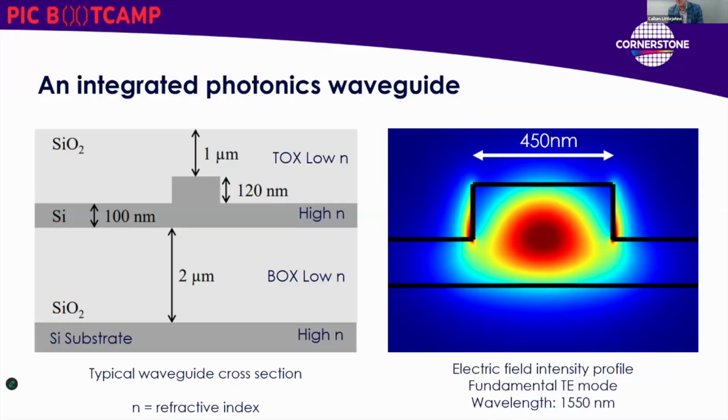This is probably my most technical of all of the slides. I just thought it'd be worth introducing the fundamental concept of how a photonic integrated circuit works. So what we're looking at here is a cross section of the main fundamental building block of a photonic chip called a waveguide, and it's a device that routes light around a chip. If you compare to the electronics domain, this is analogous to a metallic wire, for example. Metallic wires will transmit electrons, and a photonic waveguide will transmit photons.